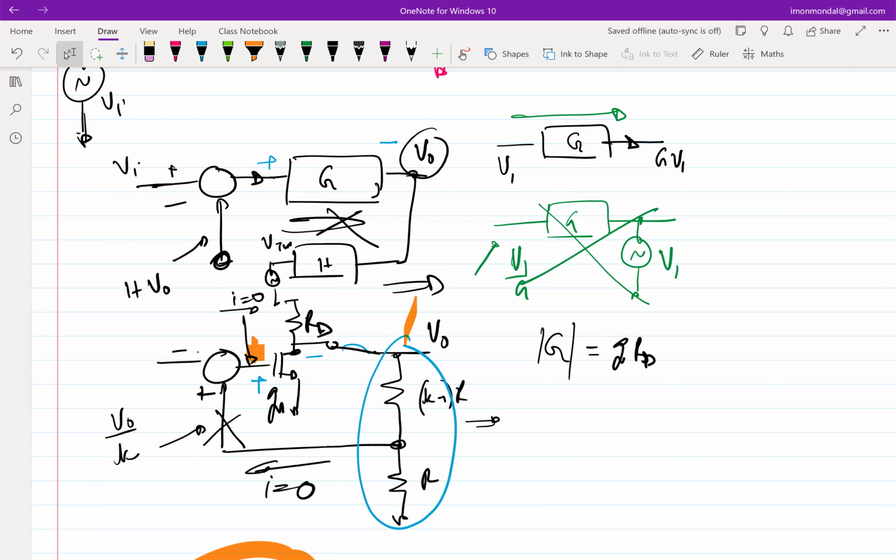Ultimately, even though we are only dealing with small signal right now, we understand that there has to be a bias in order to generate the appropriate gm. If you don't have a bias VDD, you will not have any DC or quiescent current. If you don't have any quiescent current, you will not have the requisite value of gm. But we can get the value by changing the R itself. For any given value of gm, we should alter R to set the final output.